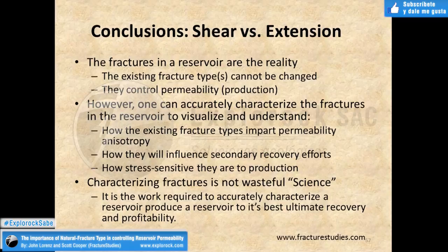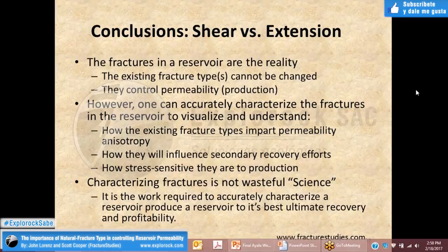Since the outcrop is at the surface, it has had different stresses on it than what you see in the subsurface. But the outcrop will give you a concept of how susceptible that formation is to fracturing. If it is fractured in the outcrop, it is likely to be more fractured, at least, than other formations in the subsurface.